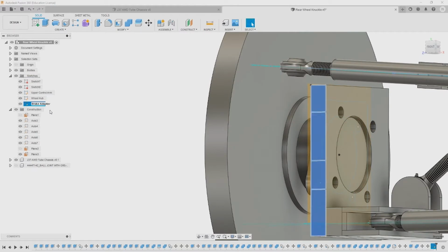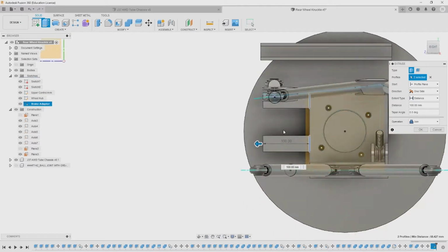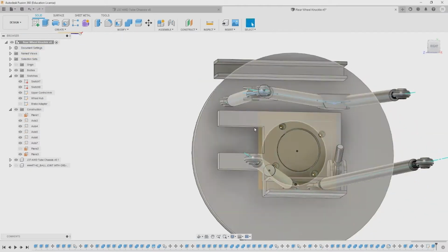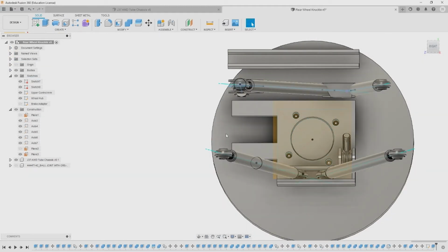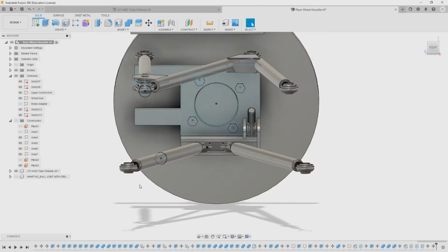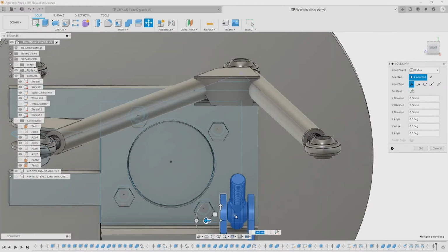Here I'm going to make some basic standoffs that'll eventually house the brake calipers, or where I'd ideally like them to be. At the end of the day, a lot of this is going to have to be whichever direction the calipers prefer to be. I'm not going to try to bench bleed these every time I want to change them out or change the fluids just because it looks better. They're going to go in a similar orientation to where they came from the factory in the car.